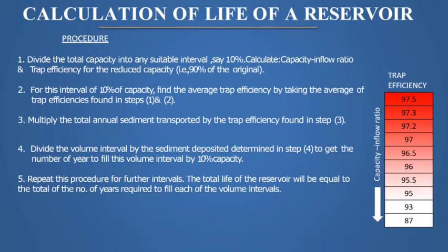To calculate the useful life of a reservoir, I have listed out a procedure which can be easily understood if you have a grasp of the concept. Initially there will be some inputs given to us. That is, inputs that tell us how much sediment is coming, how much inflow is coming, what capacity it has, and what the relationship is between capacity inflow ratio and trap efficiency.